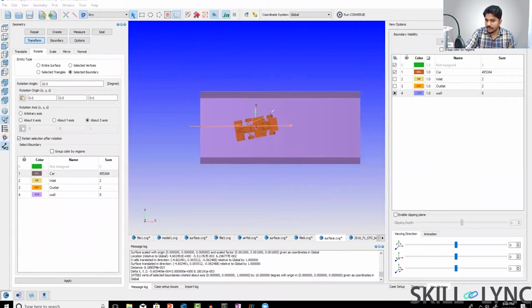Your flow is asymmetric, right? Your flow is asymmetric. So this is going to cause a difference in the downforce between one side of the car and the other side of the car, right? So you need to understand that. You need to make sure that you're still getting the required value of downforce so that you can make the turn in a proper manner.